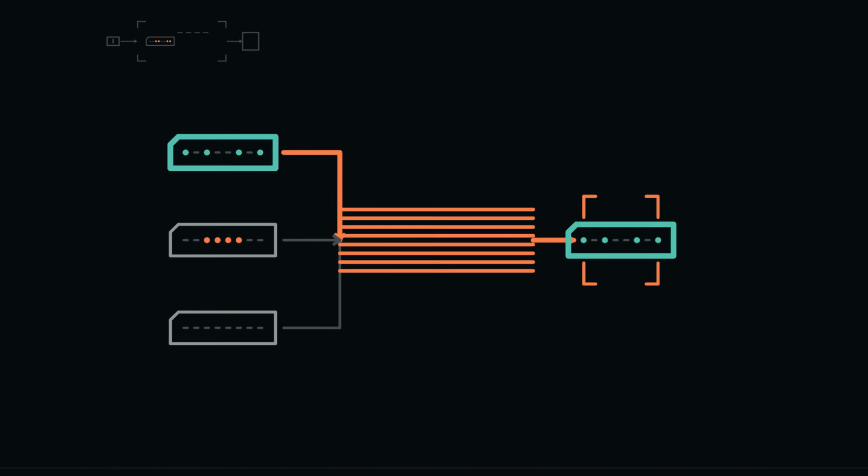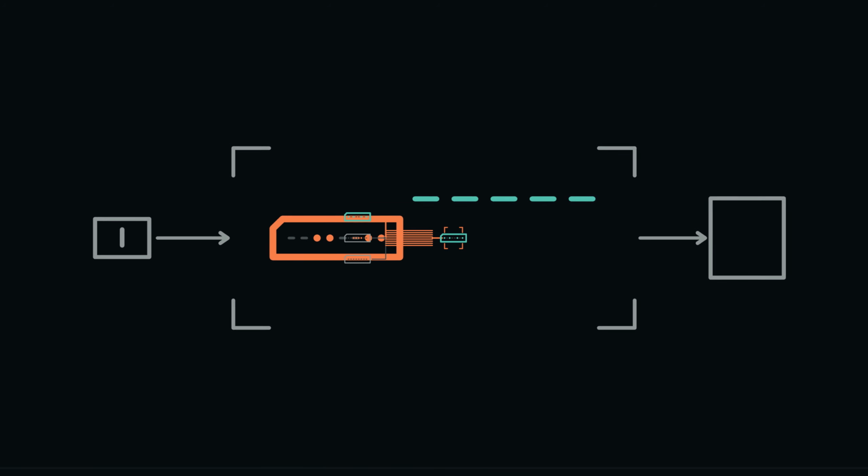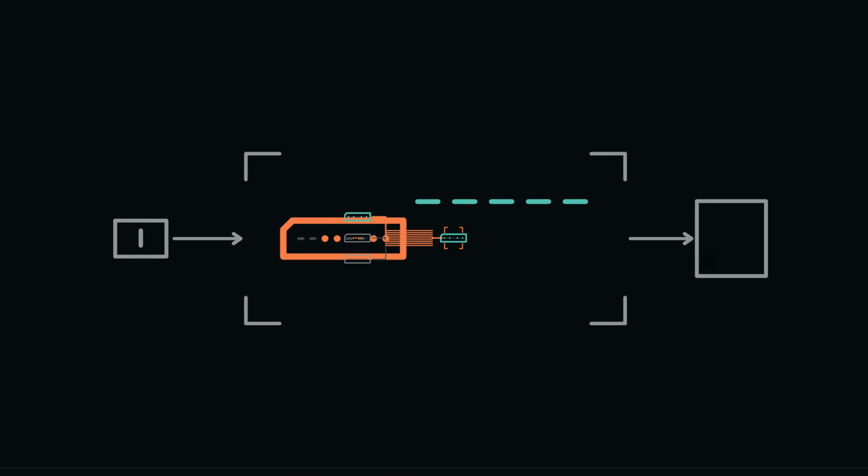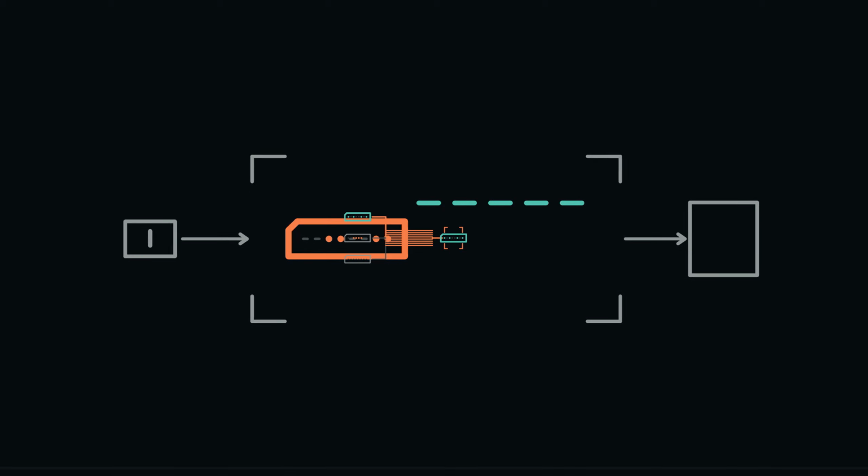Representation is the physical condition used for each bit. Value is the abstract ordered pattern. Location is the state holding component that currently preserves that value. Transport is the controlled causal relation that lets a destination capture it. The bus solves transport by sharing 8 lines under a one-driver rule. It supplies neither memory nor meaning.